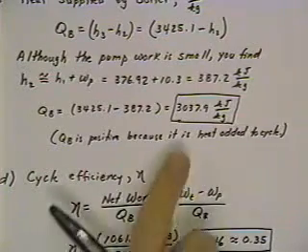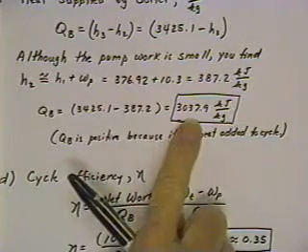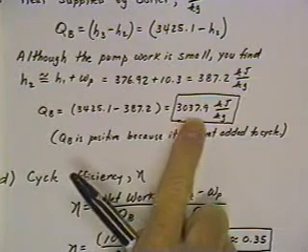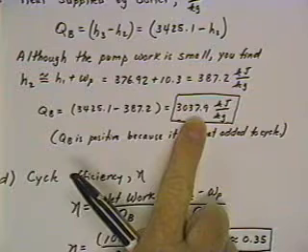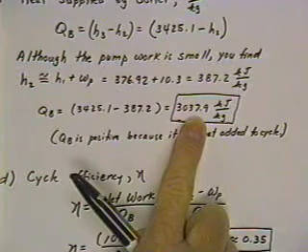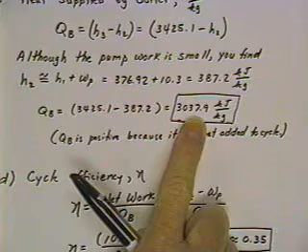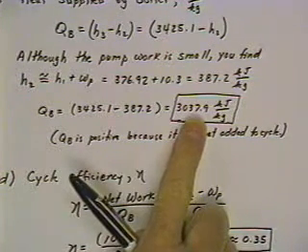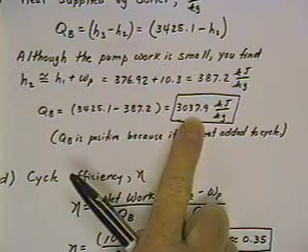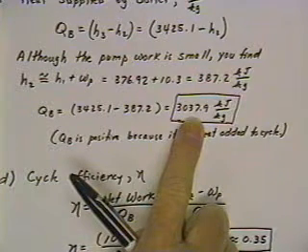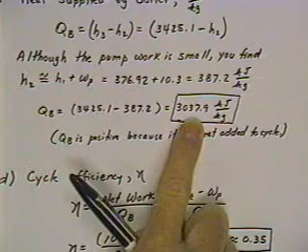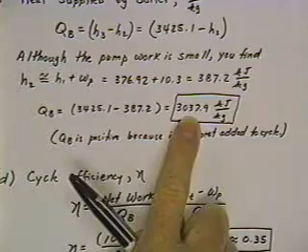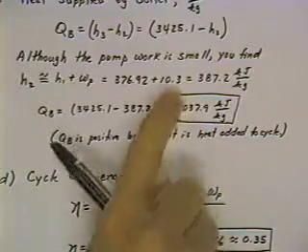one of the answers to be 3047.9, or roughly 3048, because it would be what is called a distractor, and it would be a very common mistake to ignore the work of the pump. And so anytime that you find two answers that are real close together, you have to be real suspicious on the exam, because one of them is likely to be right and one of them is likely to be wrong by ignoring something like the pump work here.